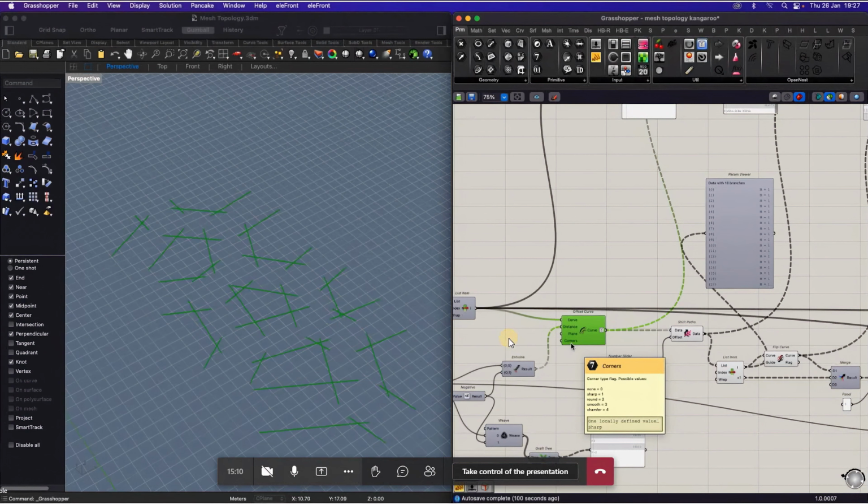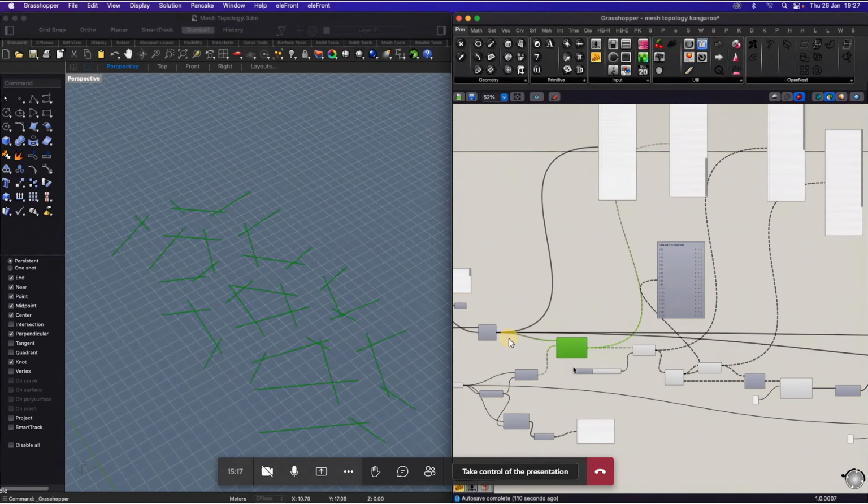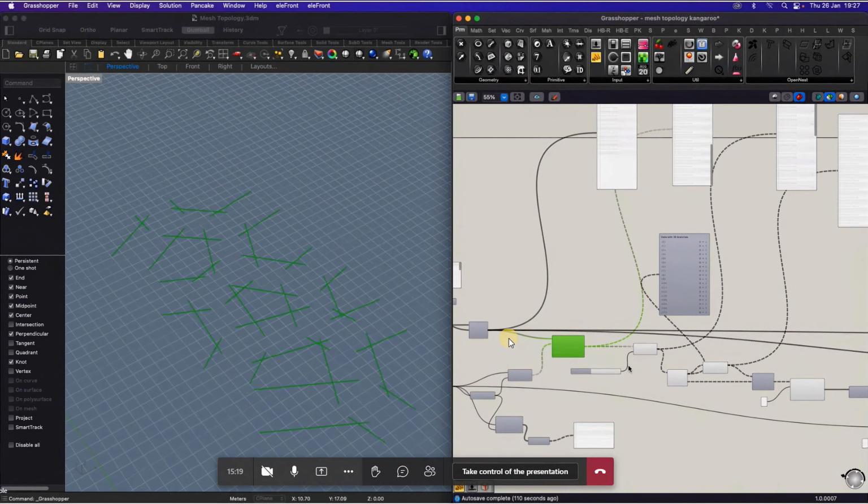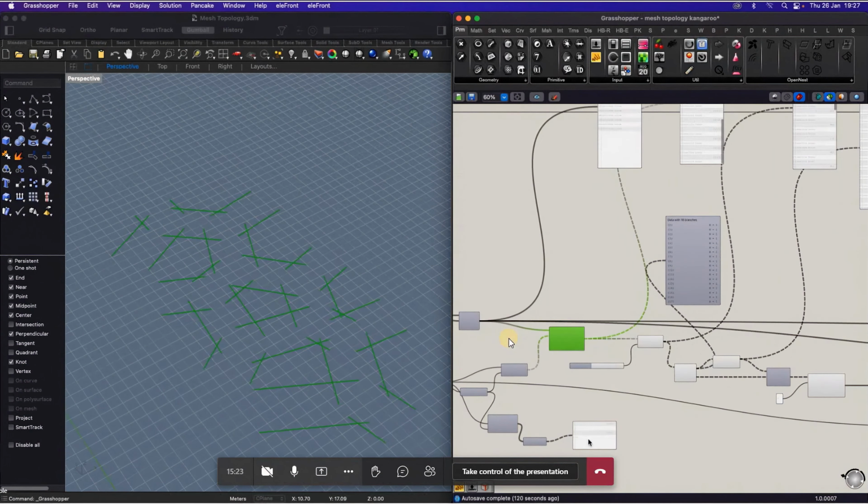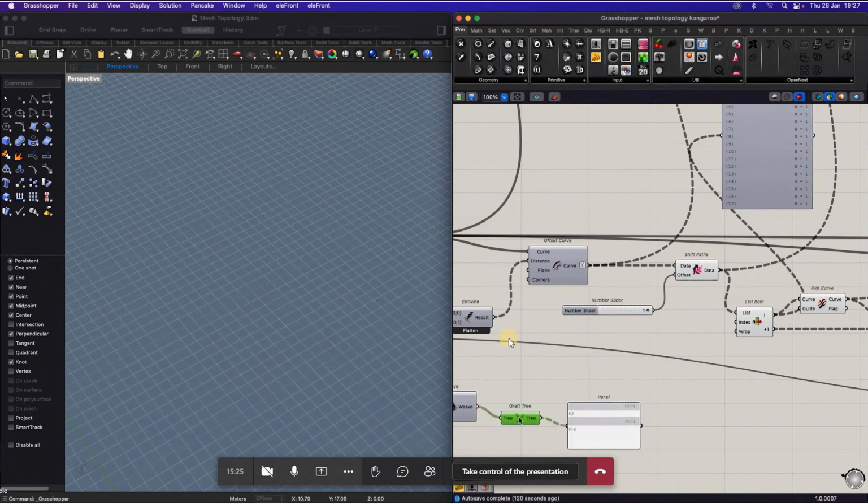In the beginning it really threw me, because sometimes you just think that the lists are equal lengths and then they aren't. Grasshopper is also very fussy like that. If your data trees or your data lists don't match when you're trying to work on both together, then it just doesn't work.